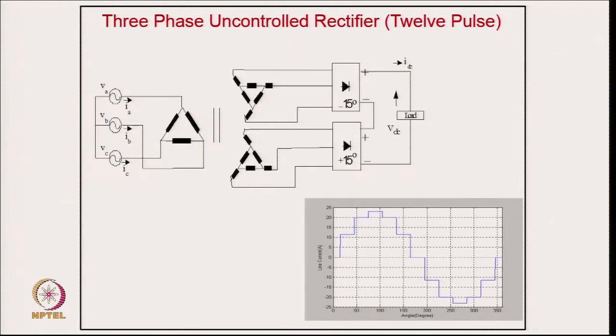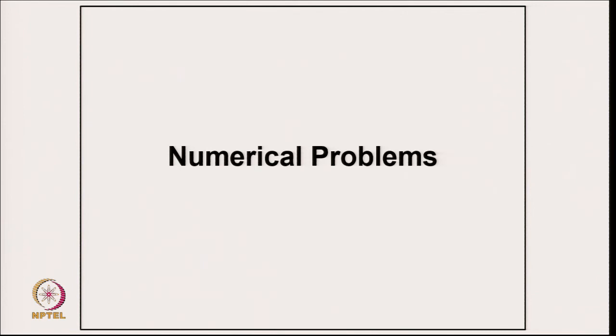And this is a 12 pulse converter. In the supply here, because of 12 pulse, you will not get harmonics lower than the 11th, and the current is closer to a sine wave, but you still have around 15 to 16% total harmonic distortion of this current.